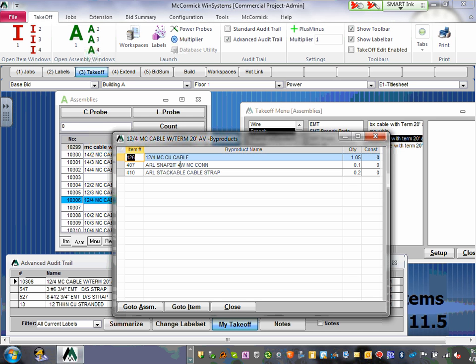Can I get you, please, to understand? Here's the tool that you're going to spend most of your time taking off, guys. You're going to be looking at 12/4 MC and 3/4 of an inch EMT conduit. Doesn't mean you can't use 1/2 an inch if you have a use for it, but try to move when you design your system, guys, in a building. Try to move with 3/4 of an inch and MC 12/4. That's the most economical way of doing it.